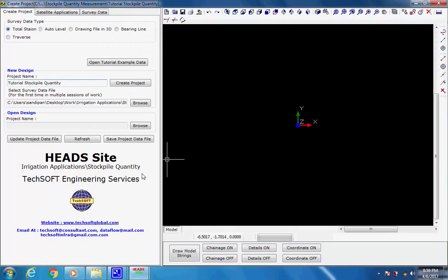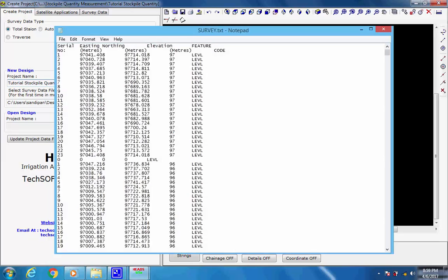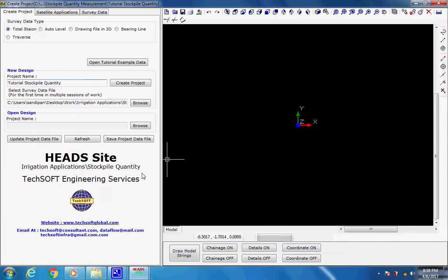Ground modeling. The data in the total station survey data file must be made available in the following format and saved as a text file, for example survey.txt, which can be opened in Notepad. It has 5 columns of data. When a data record with serial number 0 is met, it discontinues the last feature and reads a new feature in the ground model. The above data may be either in Surveyor's Transverse Mercator, TM, coordinates or in Universal Transverse Mercator, UTM, coordinates. If the data is in TM coordinates, then these are to be converted into UTM coordinates by using GPS UTM coordinates on points with TM coordinates.